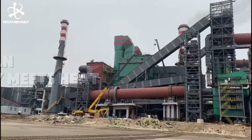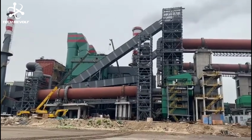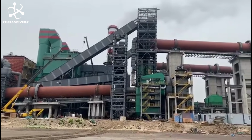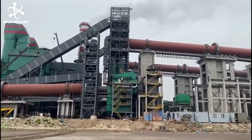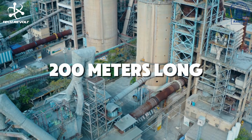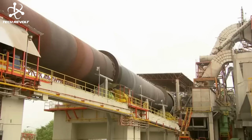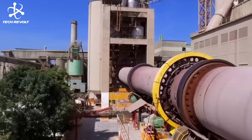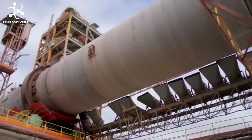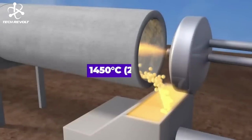kiln. The kiln, where chemistry meets heat. The rotary kiln is where the most significant transformations occur. This massive cylindrical furnace, which can be up to 200 meters long and 6 meters in diameter, rotates slowly on an axis slightly inclined to the horizontal. The temperature inside reaches an astounding 1450 degrees Celsius, hotter than most lava.